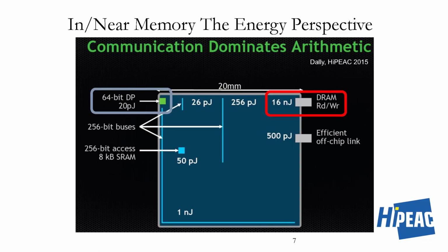So what process is this valid for? Oh yeah, this is a bit old, right? So they have done it on 45 nanometer. This is 5 nanometer. 45 nanometer, yeah, it's really old. But the trends are similar. And at which temperature? Because leakage goes up with temperature exponentially. So I think this is at room temperature.